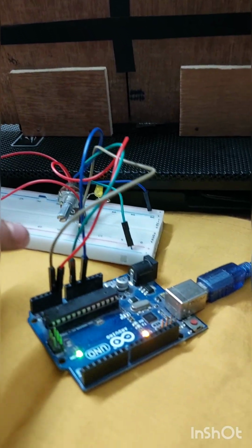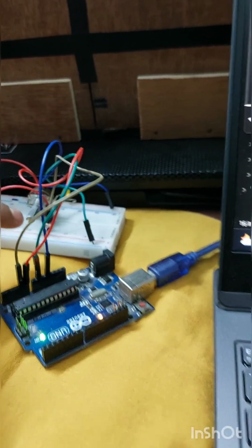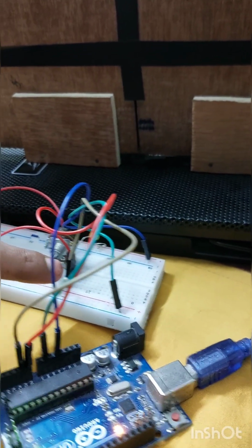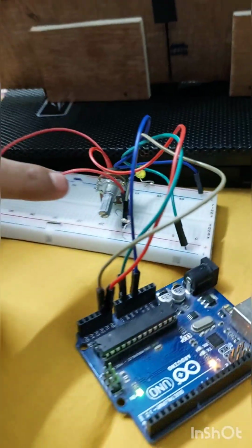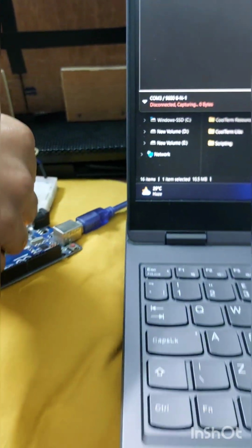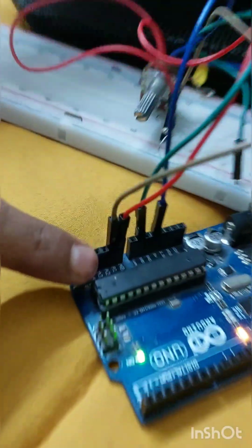Arduino is used here to get the IV curve. This is the circuit of our project. Here we are seeing the resistance, which has a 10 ohm value. This is the potentiometer with 10K value, and this is the orange LED. The two pins from the circuit are sent to the Arduino via the A0 and A1 analog pins.